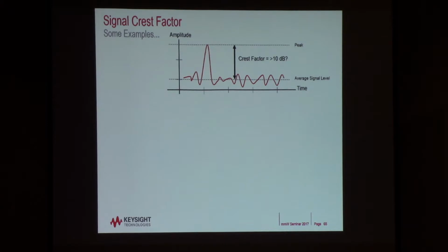So I mentioned going to wider bandwidths tends to decrease the power spectral density, which makes your signal to noise ratio lower. But the next thing that people also want to do is they always want to increase the modulation order. So we could do QPSK, but wait a minute, what if we did 16 QAM, or 64 QAM, or 256 QAM? As we go to the higher order modulations, or OFDM, the peak to average ratio increases.